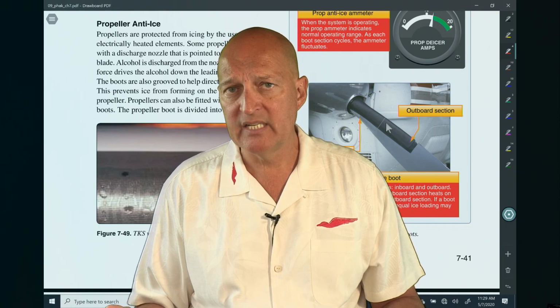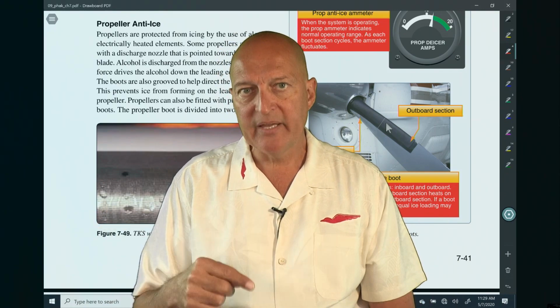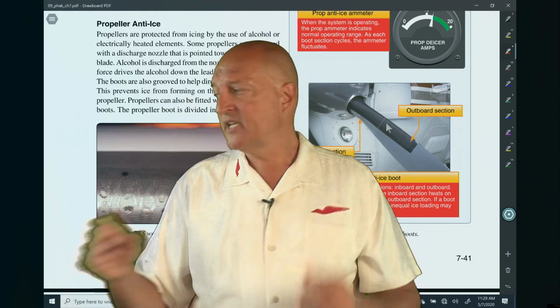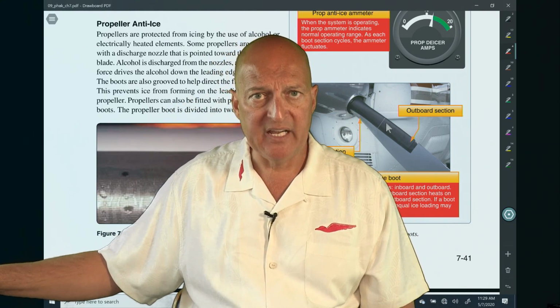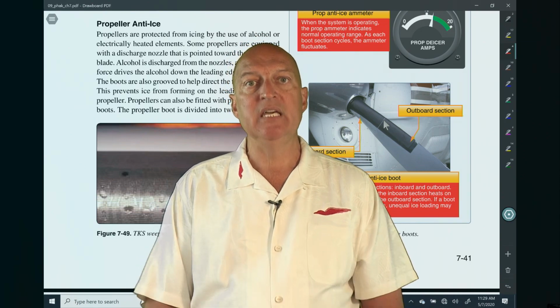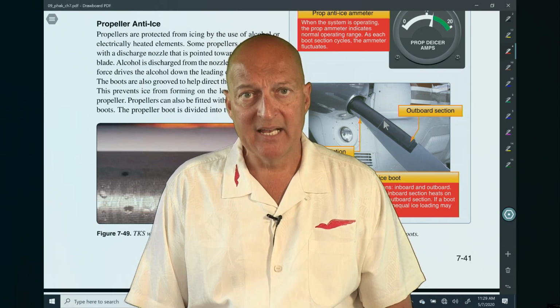Does that mean I don't have a de-ice system? Actually, my propeller has what we refer to as a hot prop. So those lower elements here, where it's slower moving, are going to be the areas on a propeller that could be more susceptible to developing ice, where that slower movement closer to the hub here in this inboard section of this propeller. So there's a heater that actually can heat that element here to help keep that ice from forming. Now, it is a big amperage draw on my electrical system.